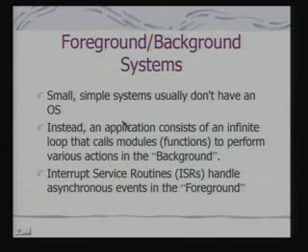Small, simple embedded systems usually don't have an OS. Instead, an application consists of an infinite loop that calls modules or functions to perform various actions in the background, because it's a common flow with different functionalities to be catered to. And interrupt service routines handle asynchronous events in the foreground. This is the basic structure for the more common systems.